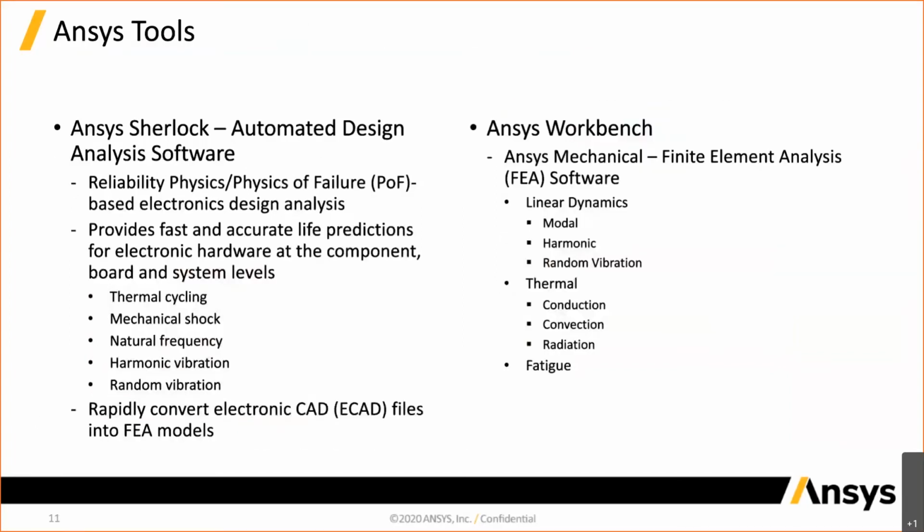Really quick review of our Ansys Sherlock tool. It is a reliability physics of failure approach to electronics design analysis. You give it all your PCB fab data. It could be Gerbers, ODB++, or the IPC format. Bring those in. You can bring in the bill of materials.